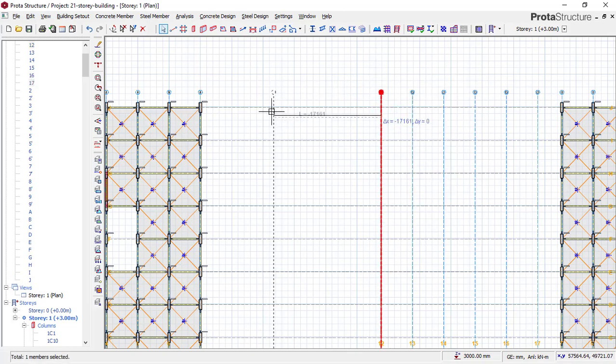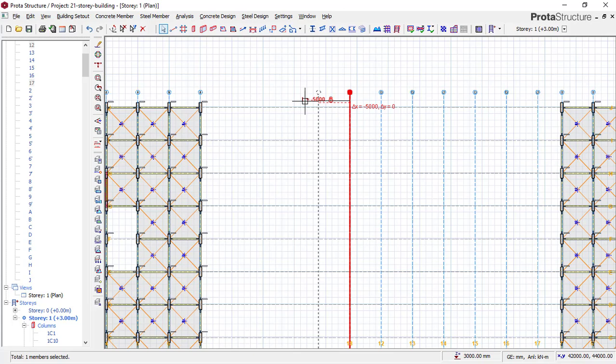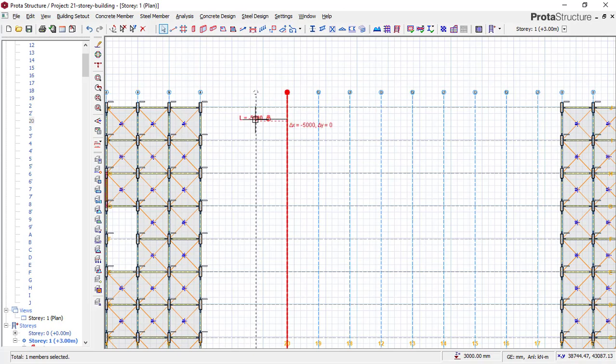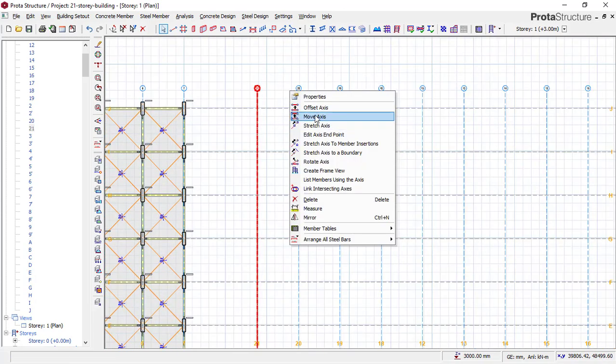Again, offset to have this here. We hold shift F2, negative 5 meters. Enter. We enter again, repeating for each grid line, and we enter again the last time. Okay, so we now have, okay, that one didn't pick up, so let's offset again.